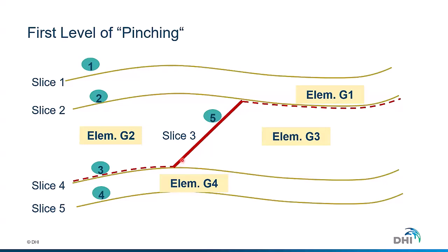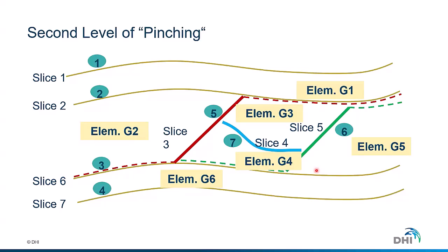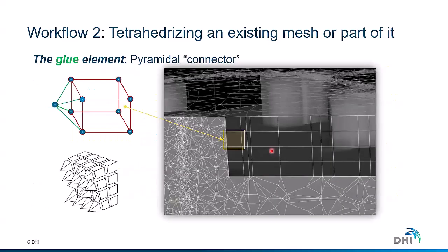And if there is interpolation happening in this slice in red, then FEFLOW will know where to stop this slice in between, which will allow you to create a number of folds or such configurations where you have a layer in between folds, or a surface is crossing a geological fault, where you have a slice on the left side or on the right side, or any other case. So this workflow one gives you a number of options, and it's quite simple to use because you just need points, and using interpolation methods like inverse distance, kriging, or Akima, you can achieve what you want.